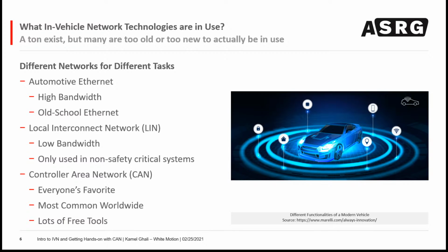that needs to be processed, for example, from a camera, right? If a camera is sending high quality image data for image analysis inside an ECU, it's likely going to be connected by Ethernet or some other high bandwidth automotive technology. Ethernet's not the only high bandwidth one, but I just included a few examples here today.